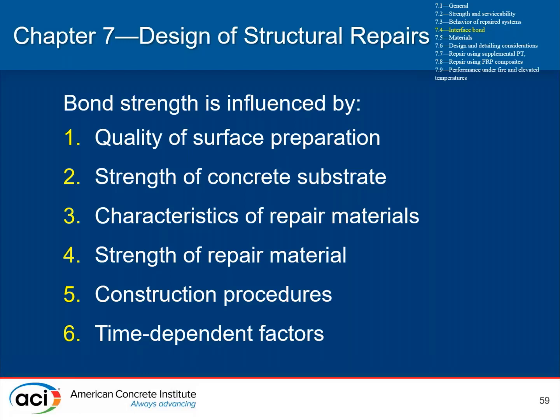And then construction procedures can impact, and the most notable one is how to condition the surface. Whether it's saturated surface dry, whether there's a bonding agent, these sorts of things can significantly impact the bond capacity.